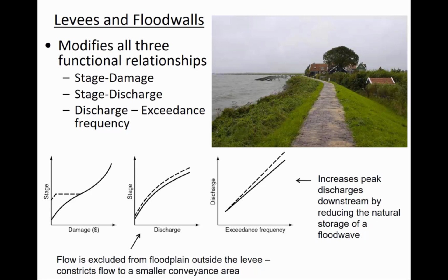And so they've got this initial failure where the water's just starting to slowly go over the edge of the levee, but then when it gets a little bit higher, you instantly get up to all of the damage level that you would have had, because all of the areas that are low-lying are going to be filled with water once that levee fails. And so, how are you protecting the people? Well, number one, the depth versus damage relationship has changed.